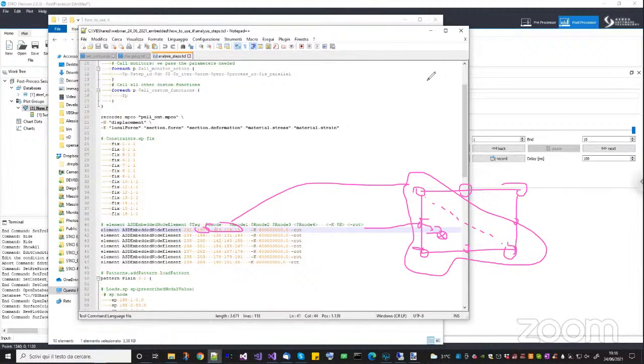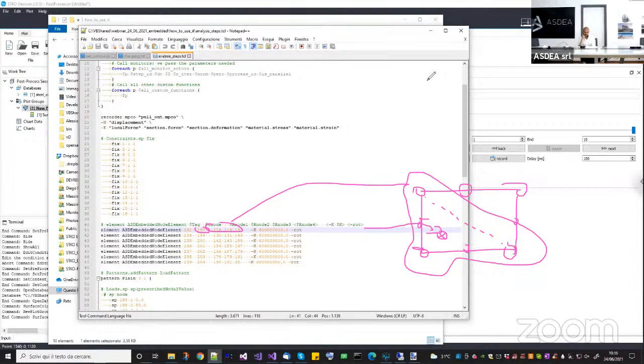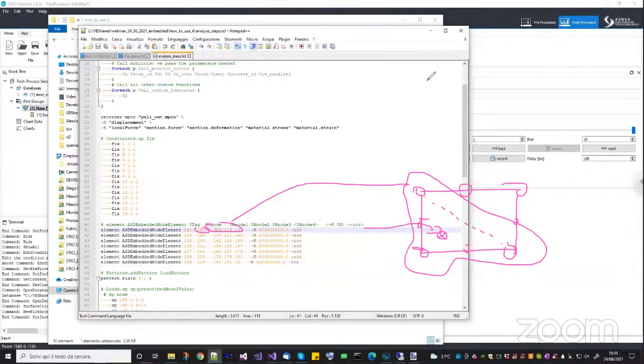Okay. So what I wonder is, when OpenSees is calculating the stiffness matrix, it asks this element to return the stiffness at the start of each factorization process. Exactly, yes, like any other element. So that means that, for example, if I use the linear algorithm, and if I use, let's say, factorized once, then this constraint will not work, or work. What do you think? No, it will work.